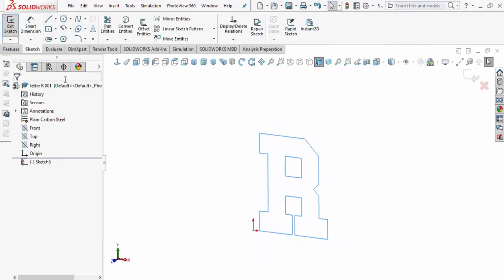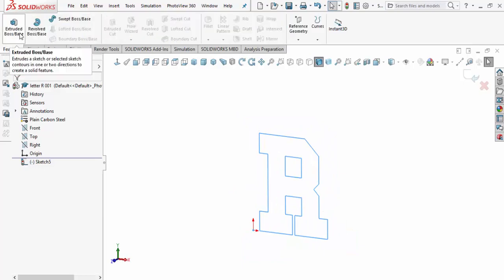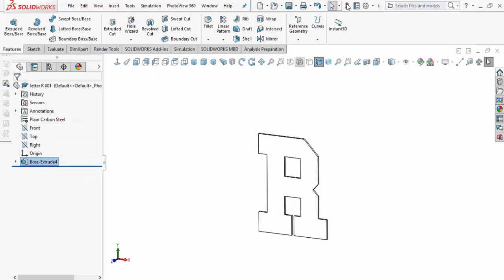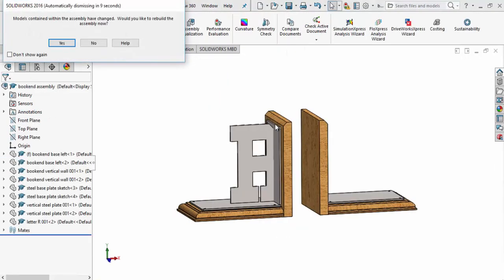Looks pretty good. So again, our thickness does maintain the same size. We're going to go ahead with the thickness of 1/8 of an inch, already set because of our last setting. We'll accept that. Let's double check we're set to plain carbon, which we still are. We'll do a rebuild and a save. Now we'll go back to our window and select the assembly, and it should come up and ask us if we want to change that.